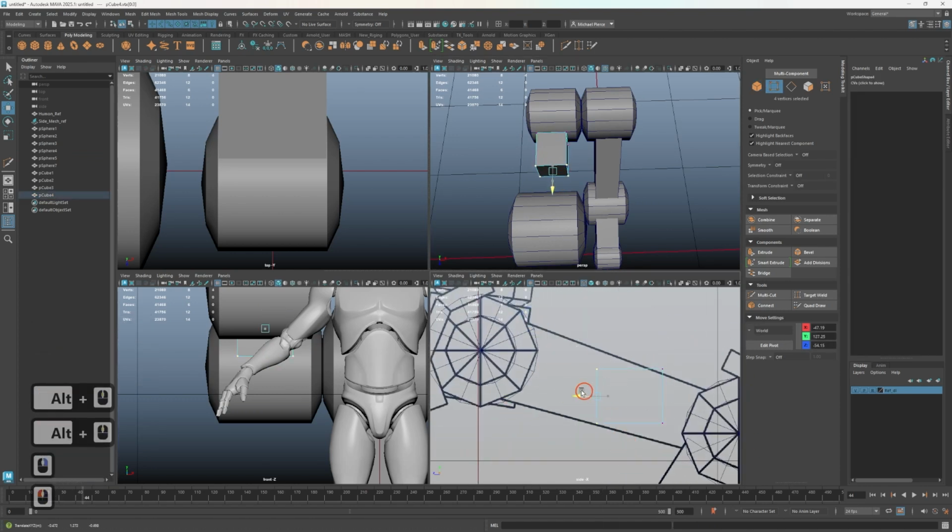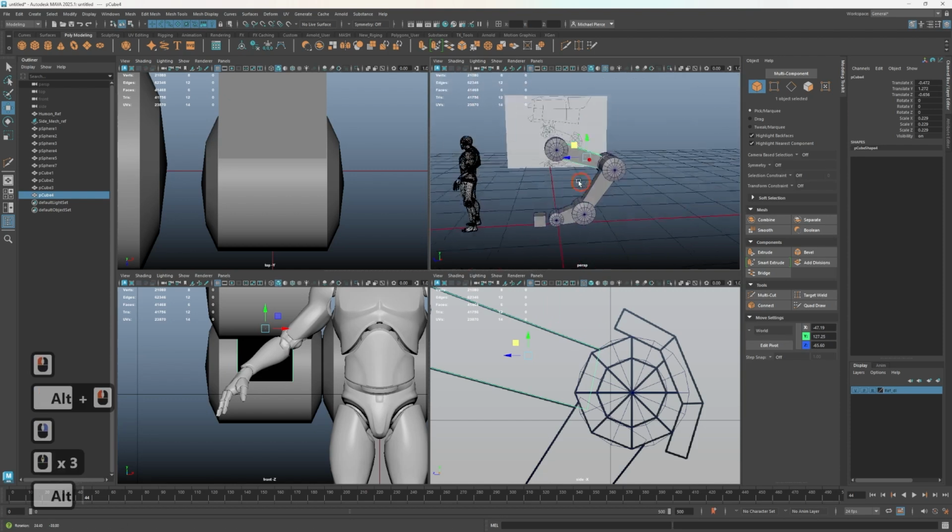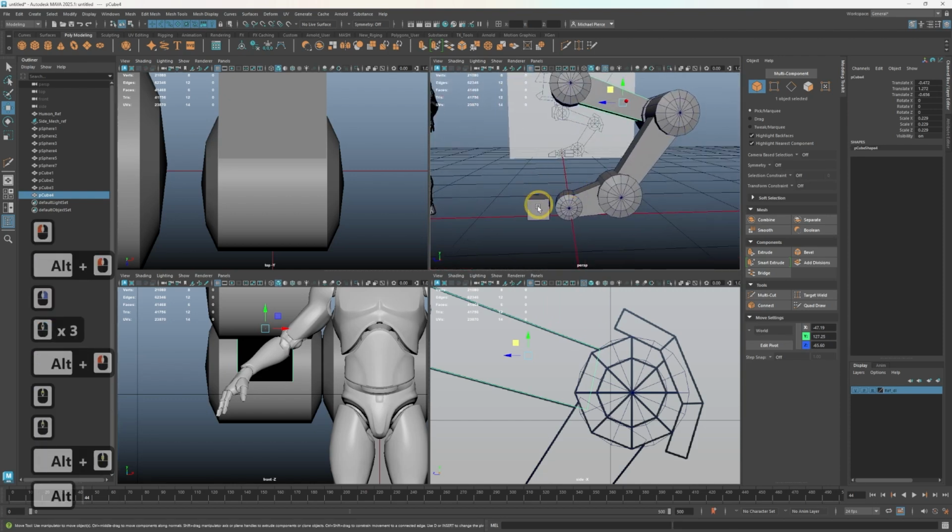And then I'm just going to drag these guys up, grab them manually, one top square by itself, right? So I'm grabbing 2 vertices at the same time just to make sure that we still have a nice square bar, and we crash them through like this. Eventually I am going to be deleting the inside faces, but that'll be when we get into cleaning this part up.